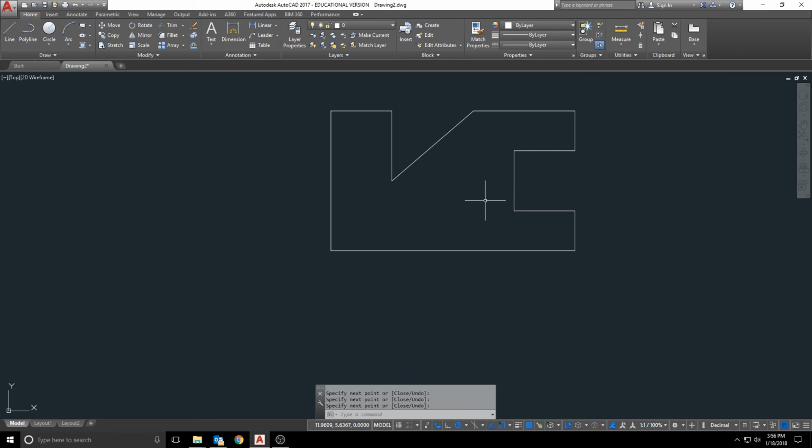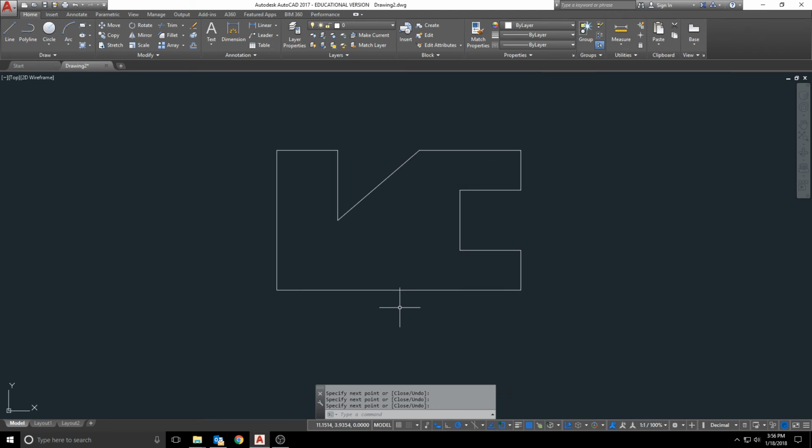So this is the first exercise, and if I want to verify the dimensions before I turn it in, I can left click here and just hover, and it'll show me that that is 6 inches. If I click on this line segment here and hover, it'll show me that that's 1. I can left click here and it'll show me, well, it's showing me on the wrong side, but it's 1.5. I can also click on this line to get that 1.5.